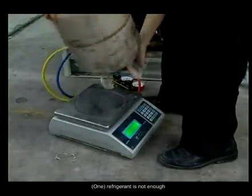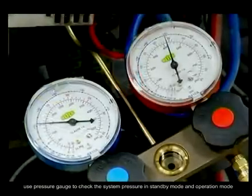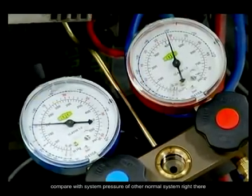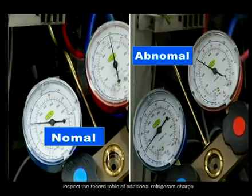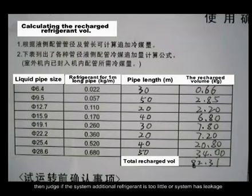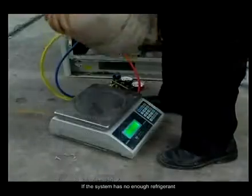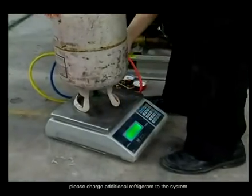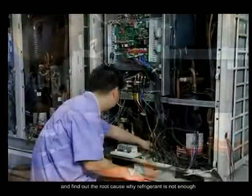1. Refrigerant is not enough. Use a pressure gauge to check the system pressure in standby mode and operation mode. Compare with the system pressure of another normal system nearby. Inspect the record table of additional refrigerant charge. Then judge if the additional refrigerant is too little or the system has leakage. If the system does not have enough refrigerant, please charge additional refrigerant and find out the root cause of why the refrigerant is not enough.